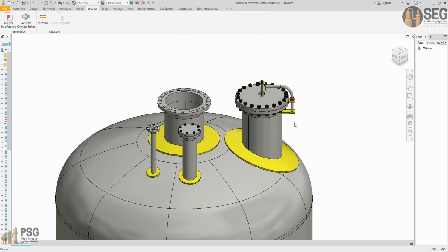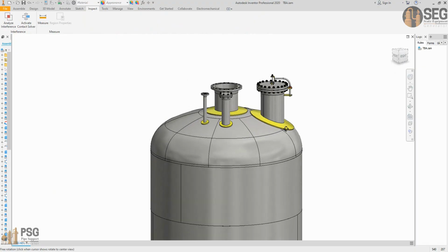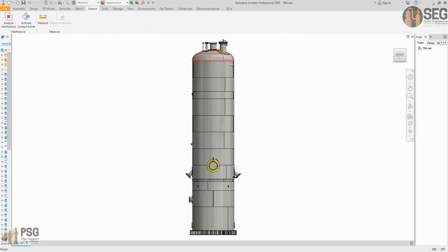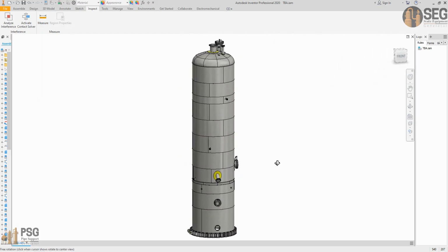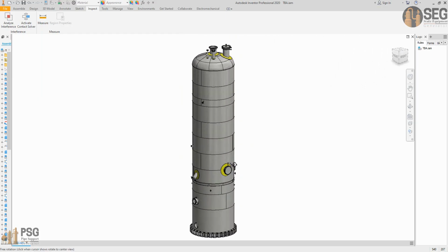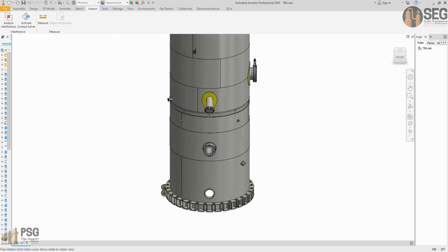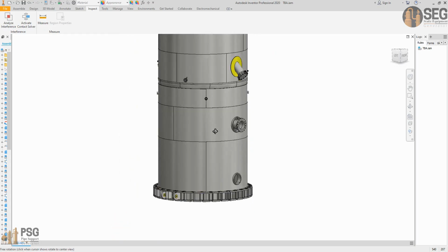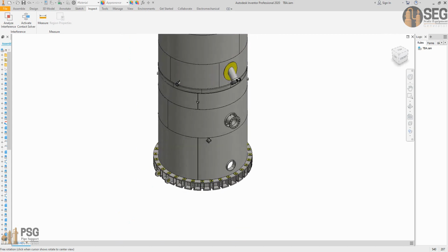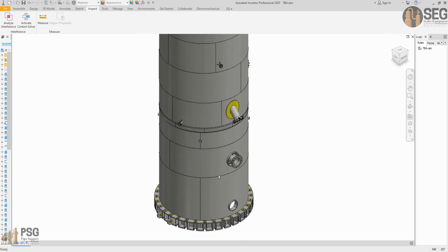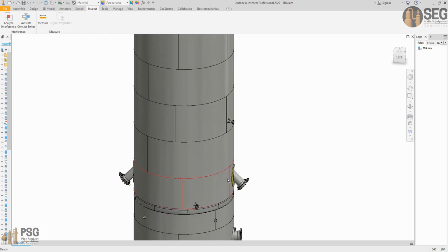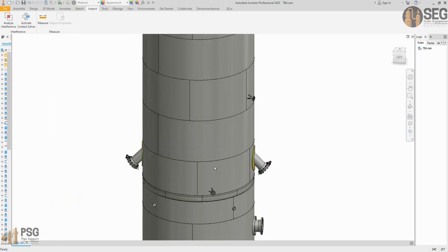And here we have the top davit on the vertical nozzle. Now, as you can see, we generated the vessel main items in the first tutorial. In the second part of this tutorial, we generated the bottom head nozzles and the nozzle openings like vents, access, and nozzle opening. In the third part of this tutorial, we generate the shell nozzles.